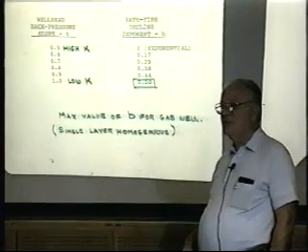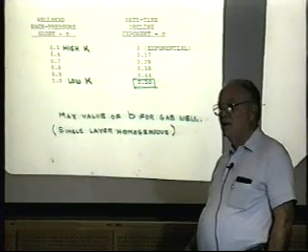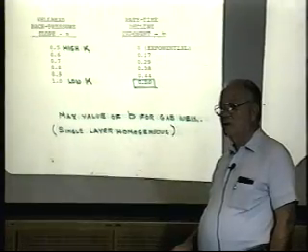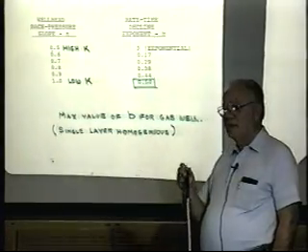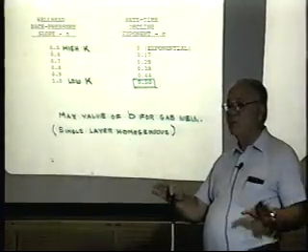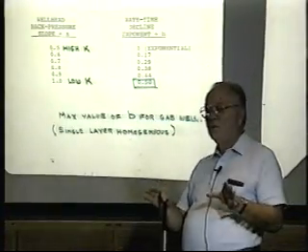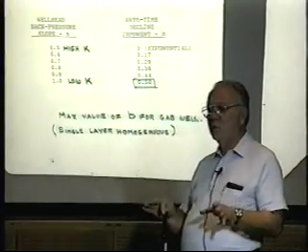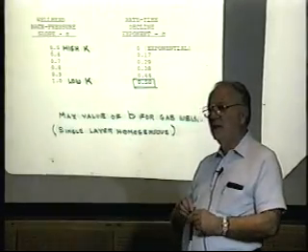It should have been cased and individually stimulated. In the early wells, we did do the individual stimulation with bridge plugs. And I'll show you some field examples, some old reports of how a lot of these reservoirs were originally completed in open hole, commingled stimulation.